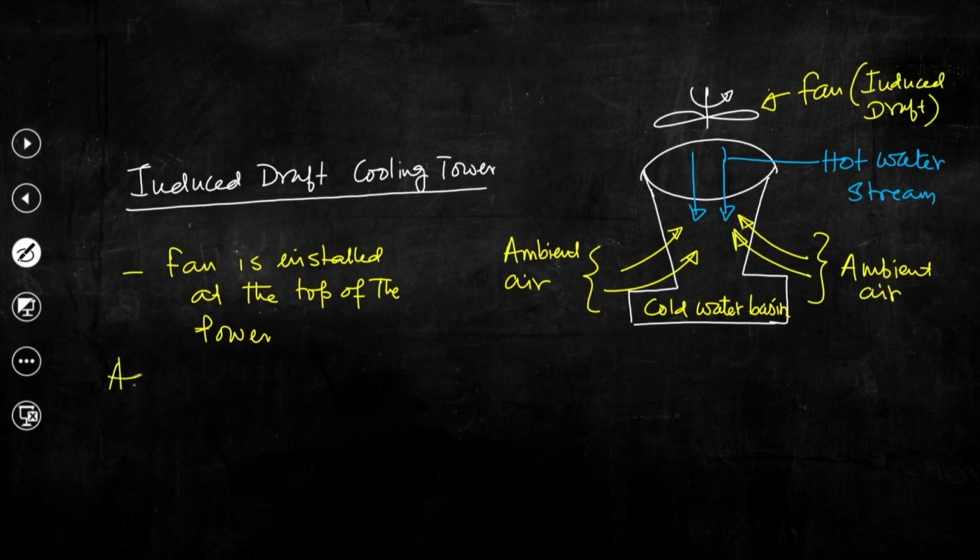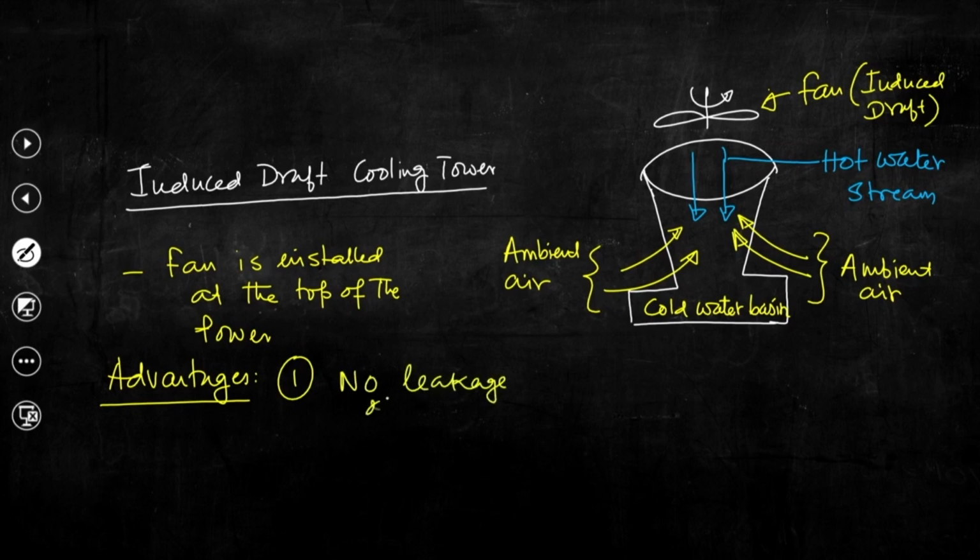Now, if we write the advantages. Number one, since air is now inducted, the pressure inside the tower is always negative. So, there is no chance of having air leakage from inside the tower to the outside. So basically, no leakage of air.